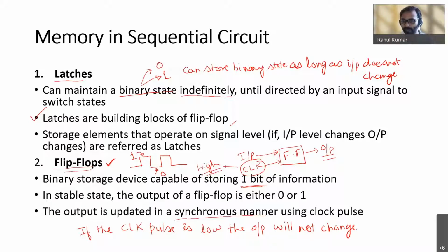In the case of a latch, as soon as you change your input, the output will change. But in a flip-flop, the memory element has to wait until your clock pulse becomes high. So there is a slight difference between latch and flip-flop.